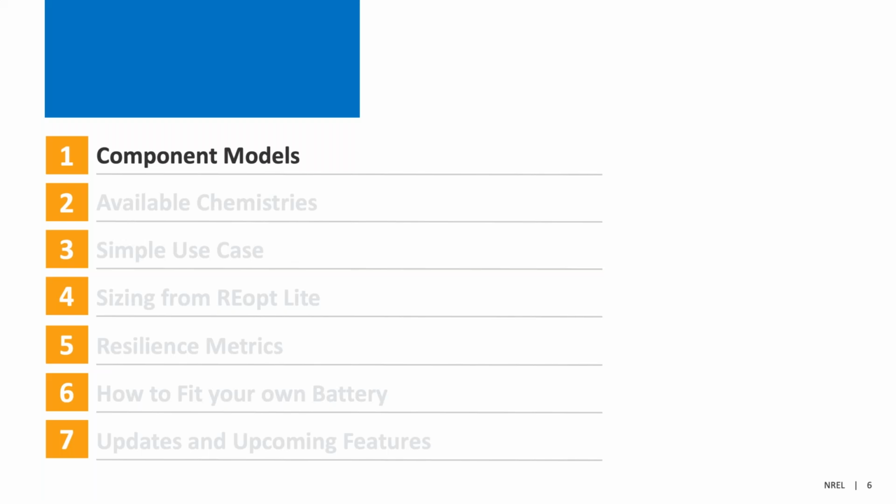So the battery model works as a composition of individual component models with interdependencies among key variables such as state of charge, current, and temperature. Most of the component models are semi-empirical, equivalent circuit or reduced order models that allow detailed modeling of features important to PV battery system design and operation, and which do not require electrochemical knowledge or data. Instead, the models are flexible in that they can be fit using publicly available data from spec sheets, papers, or charts, or they can be used for modeling batteries with raw performance test data.